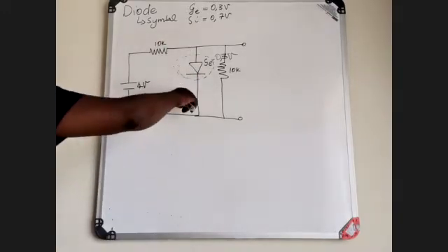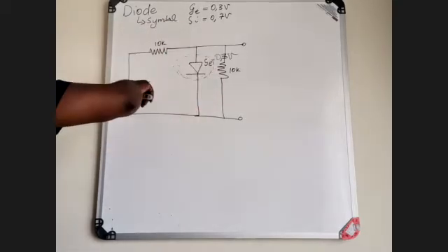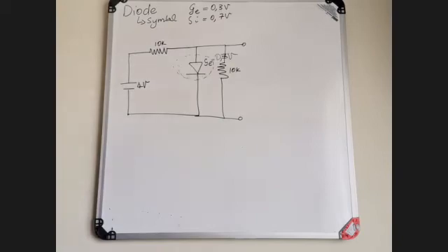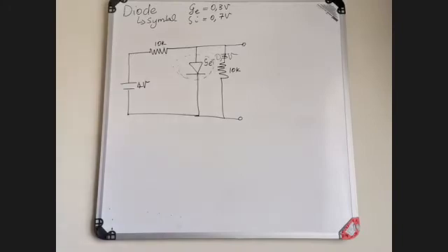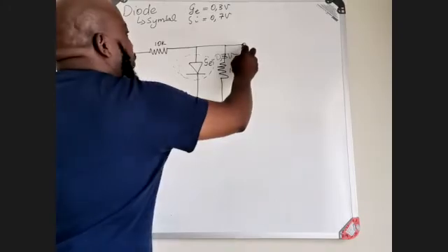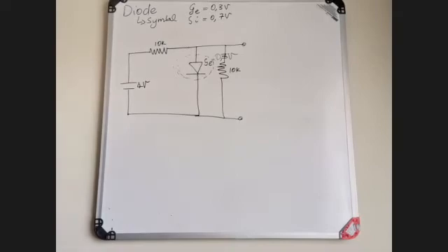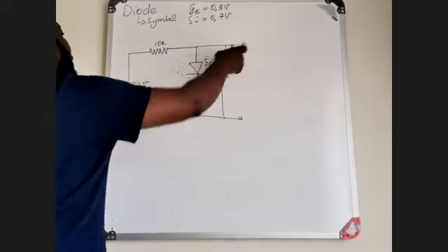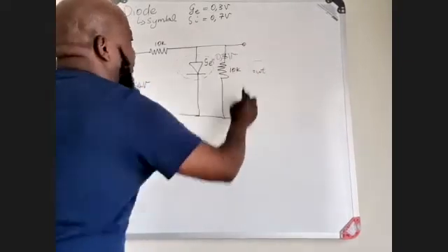So the maximum allowance of the current that is going to flow within this component, with the magnitude of that, is going to allow that component to switch on. Now, if this component switches on, then according to your understanding of the characteristics of a parallel circuit, the voltage that you're going to measure across these two nodes is going to be the same voltage which already exists, 0.3 volts.